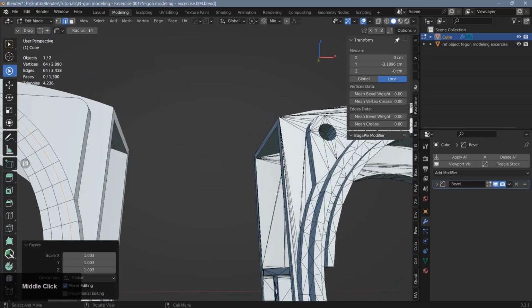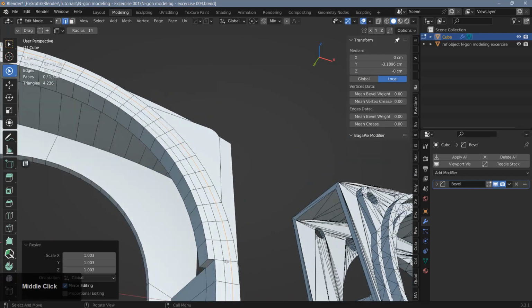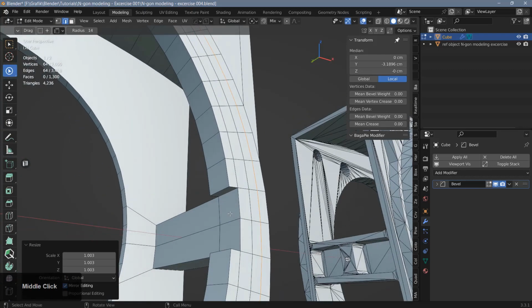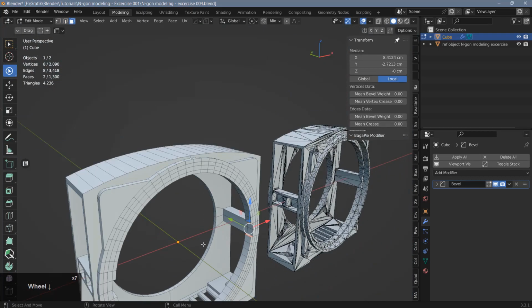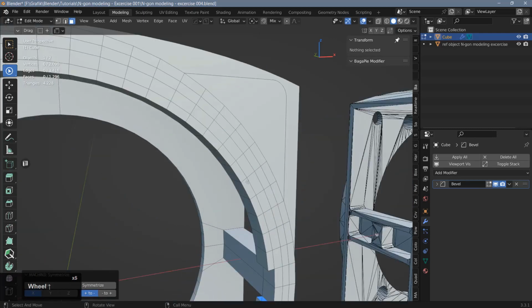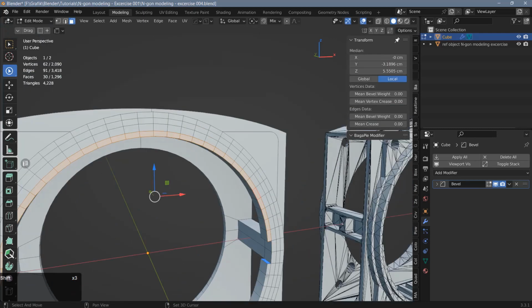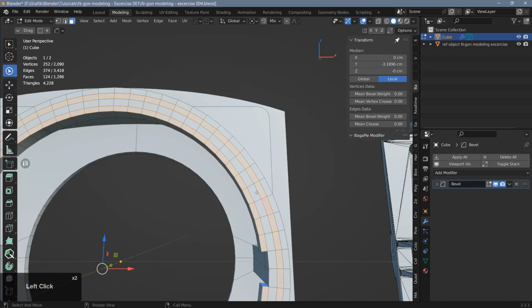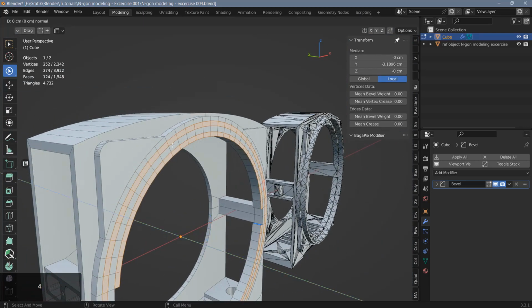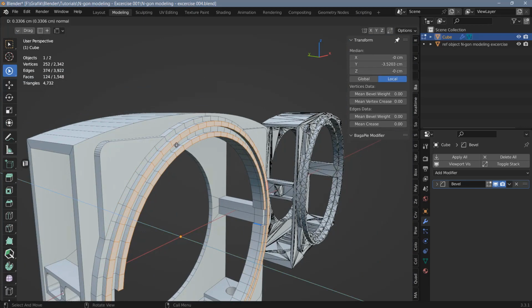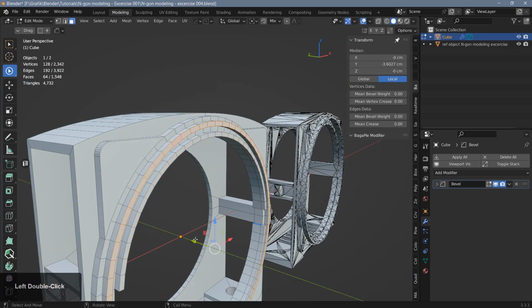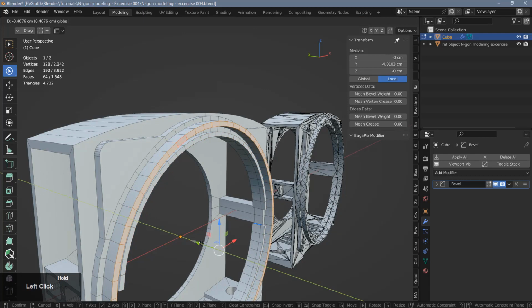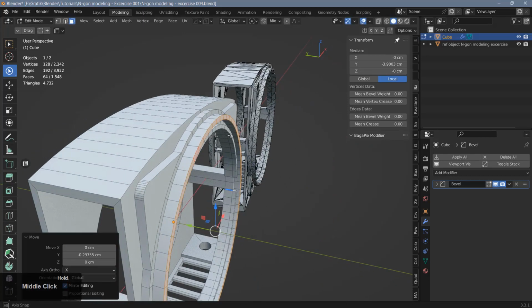We need to extrude that innermost ring and the third ring a little bit, so let's go ahead and do that. I want to make a loop selection, and in order to be able to do that, I'll just grab these faces here and delete them, and I'll mirror this over. And what this allows me to do is make a loop selection here at the front without affecting any of the other faces here. And let's grab this loop here, and I'm going to extrude this forward a little bit. Let's do something like this, and then I'm going to select this loop and just move that forward a little bit further. Let's see, something like this looks fine.